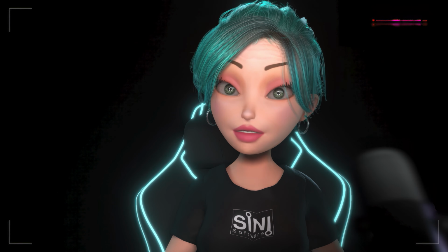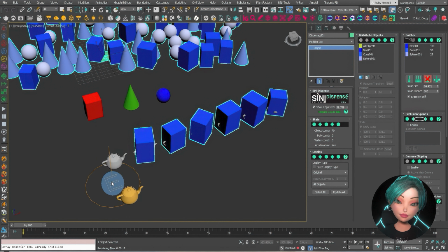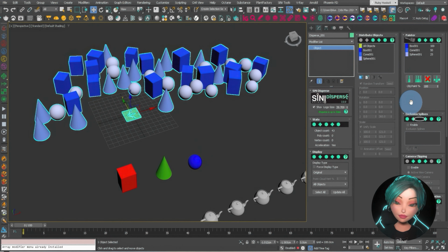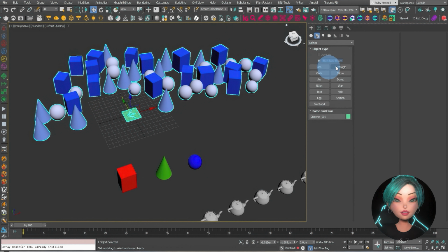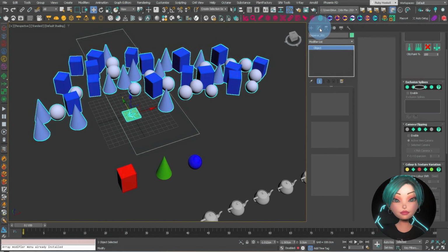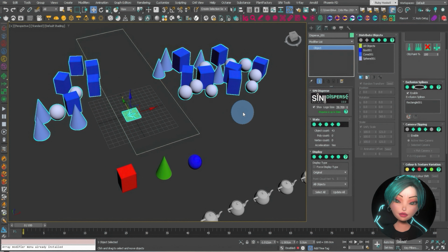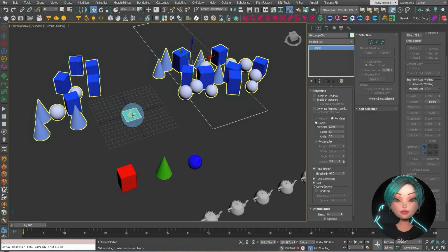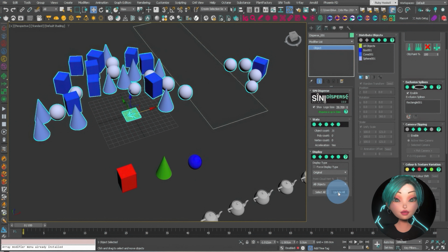Okay, time to clean up the scene before I move on. Exclusion splines. These are used to exclude areas. I'll create a rectangle. Then back in Disperse, I'll add the spline to the list. You can see it removes the Disperse objects. If I move or update the spline back in Disperse, click Update All to refresh the distribution.